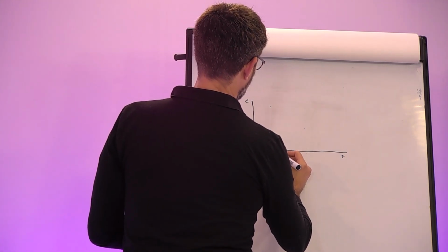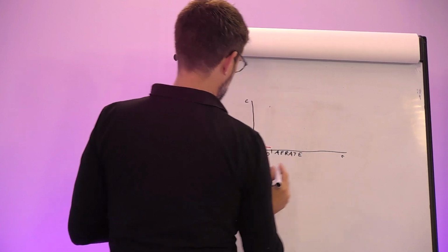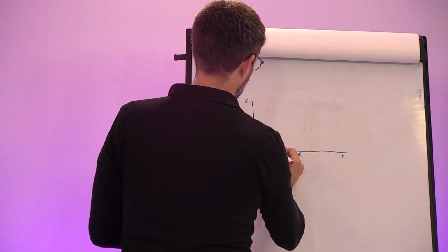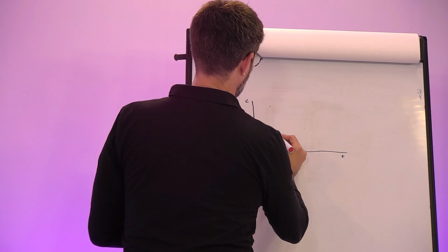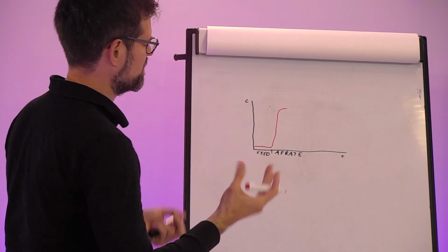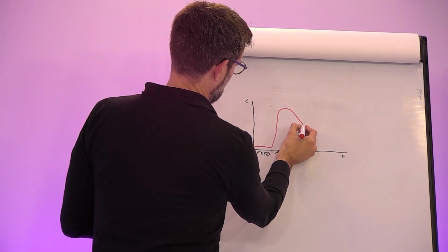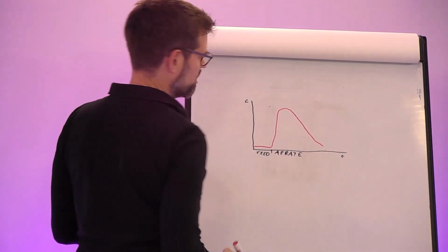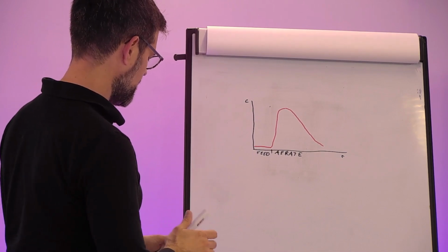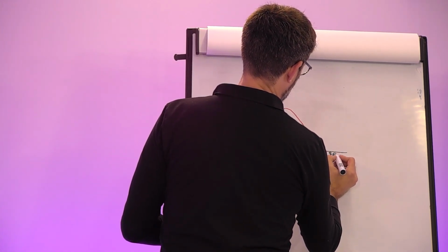We start our reaction phase, so we start with aeration. What you then see in the reactor is an increase of your ammonia concentration. It goes up because we are mixing the reactor and we meet the maximum concentration, the average concentration after feeding. During that aeration period, it will go down until we meet our requirement. Then we stop and we start the settling phase, like so, here we start the settling.